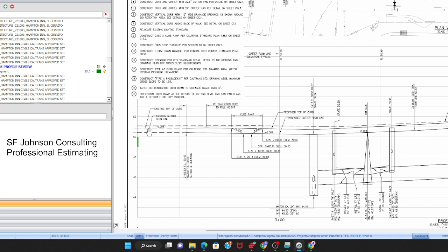If you give it a foot on each side, even for the curb, you'll be fine. So that's your 3rd dimension is 2. So this area, because it's to scale, that's going to give you an area. That's 2, and then a foot on each side of the curb is going to give you a 3rd dimension, which is 2. You see, so you'll have cubic feet. Divide by 27, you have cubic yards of dirt.